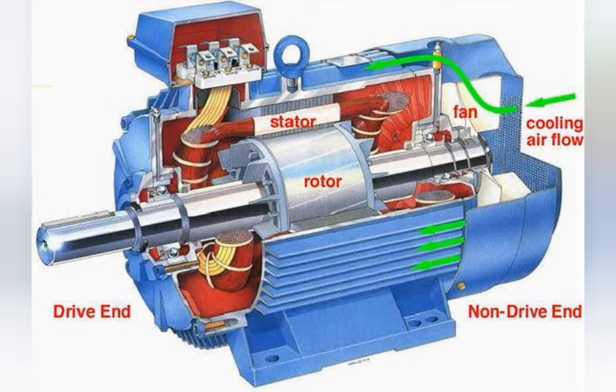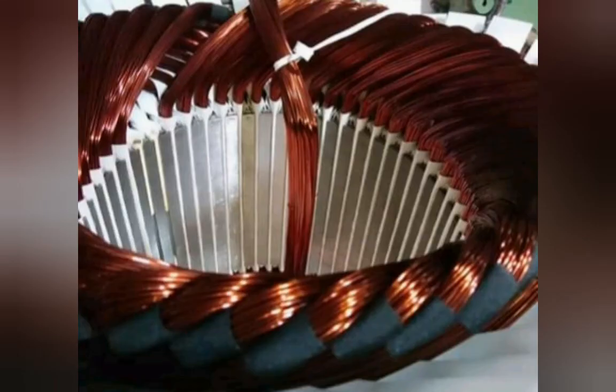The air gap is the space between the stator and the rotor. The effect of the air gap mainly depends on the gap. It is the major source of the low power factor of the motor. The end plates are brackets, sometimes called end bells, bolted to the stator. The centrifugal device is located on the rotor shaft. The stationary switch is usually located on the end plate or stator shell inside the stator, and one or more capacitors can be located on top, on the side, or inside the motor, in the junction box, or remote of the motor.